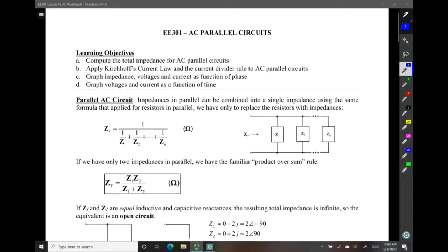And we see this right off the bat with our first formula, where we calculate the equivalent impedance for a set of parallel impedances. Everything looks just the same. We're taking the inverses of all these impedances, adding them up, and then we're taking the inverse of that quantity, giving us, again, that equivalent impedance. Also, just remember that this impedance is a vector quantity with both that real and imaginary term, which is usually denoted by bold, but I put the explicit vector notation there just to remind you.